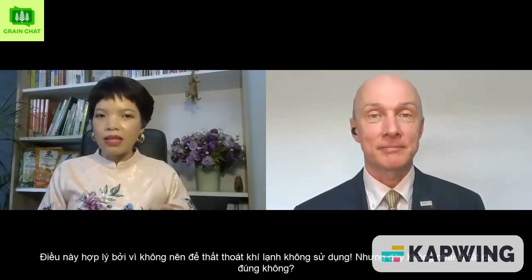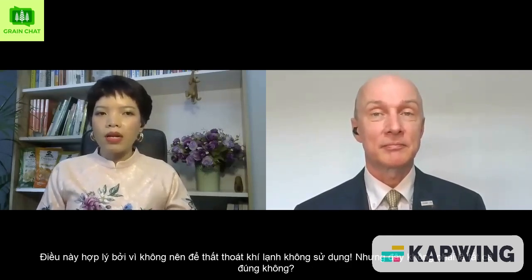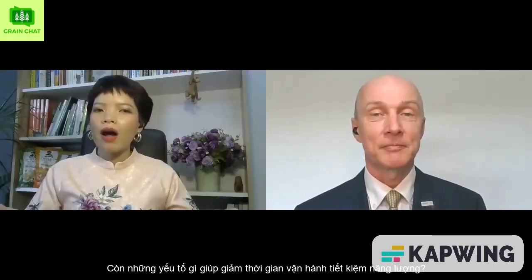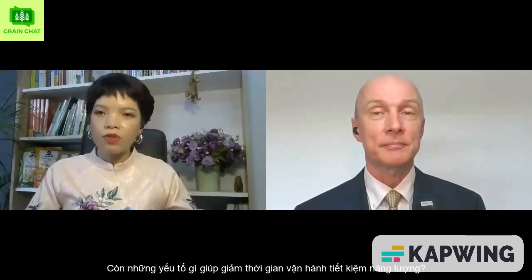That makes sense. The cold air mustn't be wasted, but that's not all, right? Indeed, the most important effect is achieved by preventing more heat release from the grain, as respiration is decreased by lower temperatures, which cuts the operation time additionally. What else will cut the operation time to save energy?